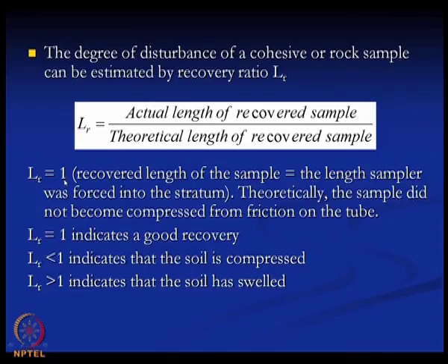Now, LR equal to 1 means the recovered length of the sample is equal to the length the sampler was forced into the stratum. That means if the theoretical length of the recovered sample is equal to the actual length of the recovered sample, then LR is equal to 1.